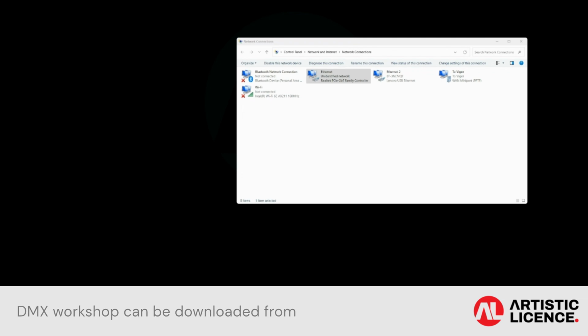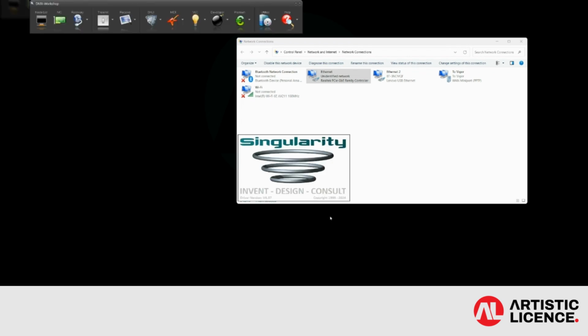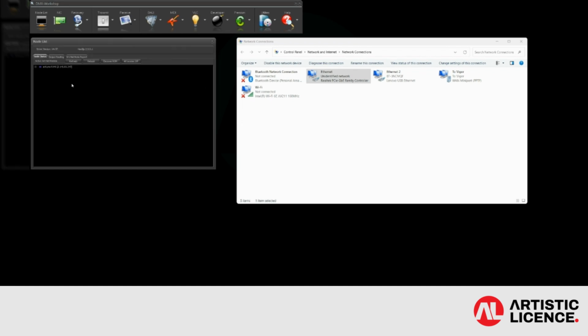If I now open DMX Workshop, I can see a list of available network interface cards, or NICs. And you can see the top of the list is the address that I just set for my network interface, 2.0.0.1. If I apply that and press OK, DMX Workshop will open. If I open my node list, Automatic Discovery will present any gateways it finds on my network.